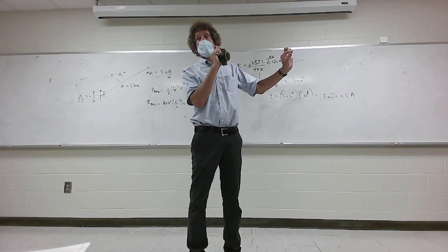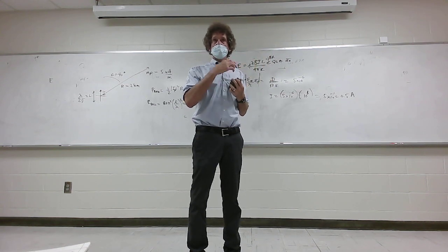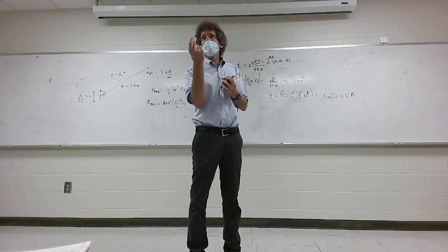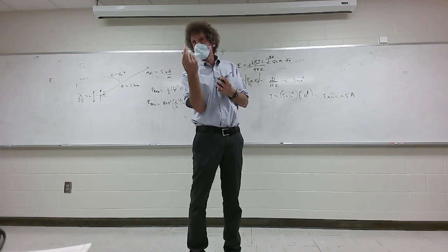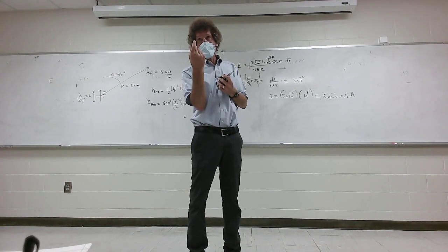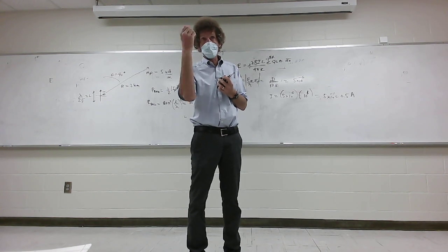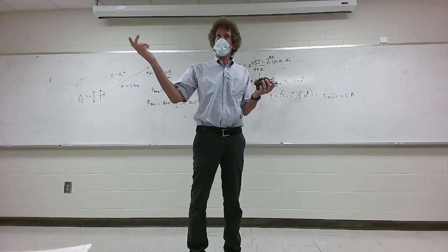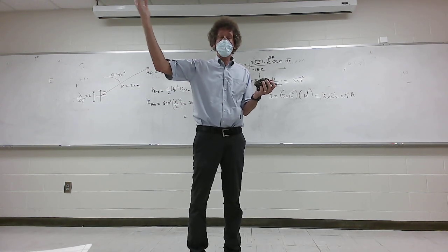Now hear me. Ideally, as an antenna person, I'm speaking from experience, what you want is a lot of radiation resistance, so you don't need much current, because current always has losses. The more current you have, the more losses due to heating, ohmic losses. That's why, as I mentioned, power lines have very high voltage and lower currents for the same power.